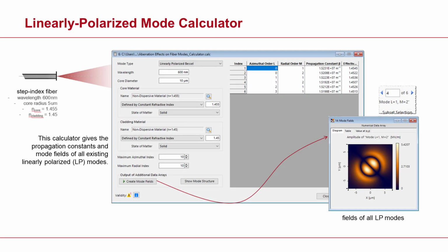Now, the experiment or the simulation starts by determining which modes propagate in our fibre. And to do that, we use the fibre mode calculator. That is the first new feature that we want to showcase, that we want to mention in the field of optical systems containing fibres. And this feature allows us to configure a specific fibre, both step index and graded index, and to obtain the modes that are propagating in it.